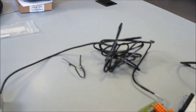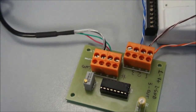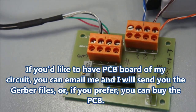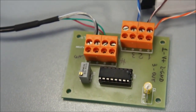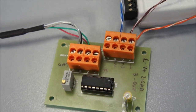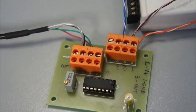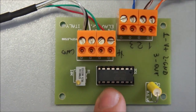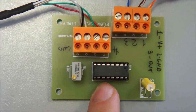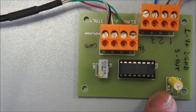Then the load cell is connected to the circuit I designed. Now, this is exactly the same circuit you find on the internet, but I decided to make a PCB board for my experimental activity, since I needed this circuit too many times, and also in printed circuit boards you get a really low level of noise. Here you see the INA125P. Here you see the potentiometer that sets the gain, and here you see the capacitor which filters the noise.